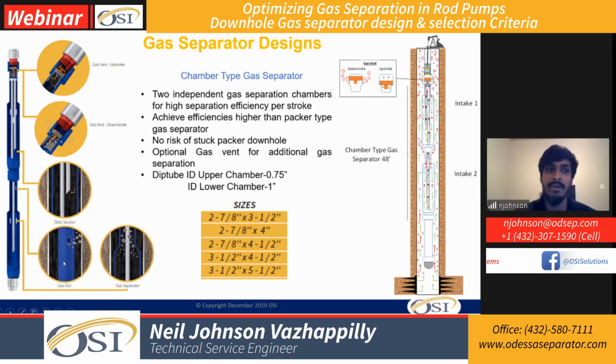After calculations and testing, we found that for 2 7/8 tubing, a 0.75 inch dip tube ID in the top chamber and about 1 inch dip tube ID in the bottom chamber gives us about a 55-45% distribution in both chambers. So overall, we have two individual separators working in conjunction with each other, giving us an overall high separation efficiency. The flow path is similar to a Mother Hubbard style, but if you look closely, we have these two slotted intakes.